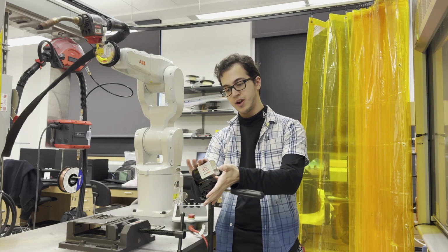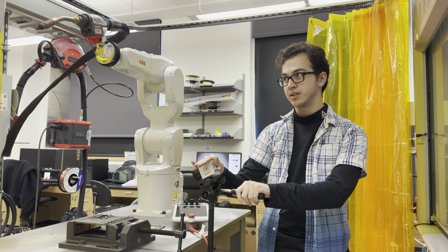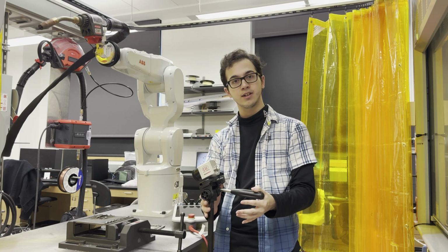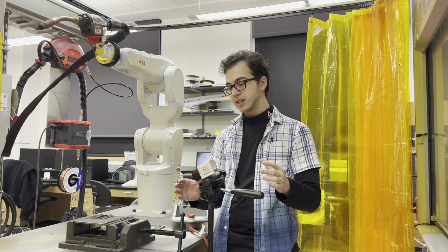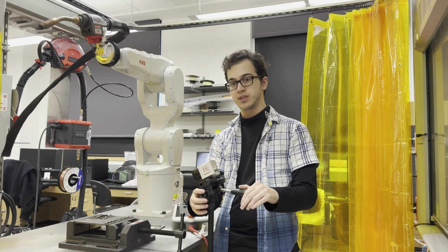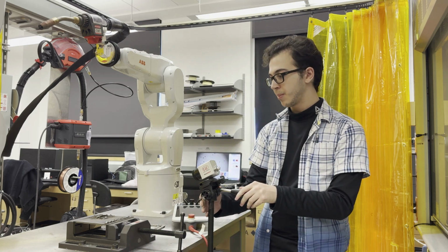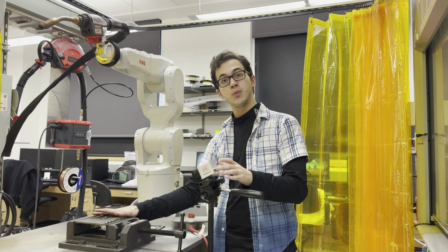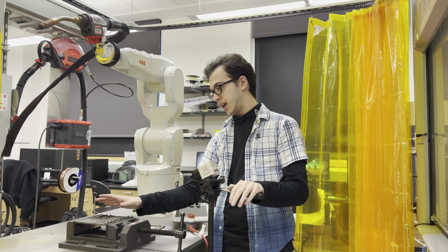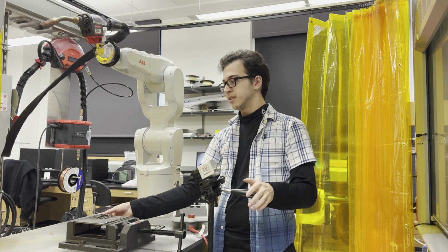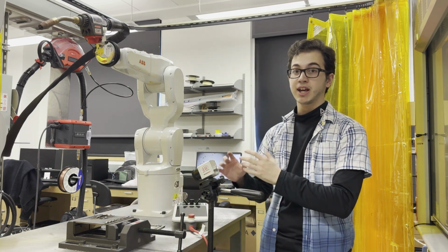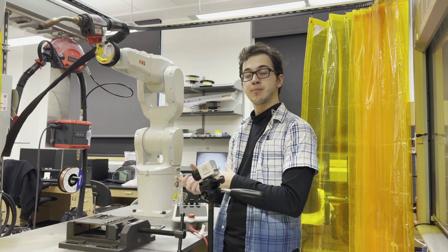This is our Micro-Epsilon thermal IR camera, and this is what we use to capture our data for our welds and the data that we are feeding into the ML, which we will talk about later. This IR camera will observe the welding process in infrared, and it'll record temperature data, and each pixel of the image is a temperature.